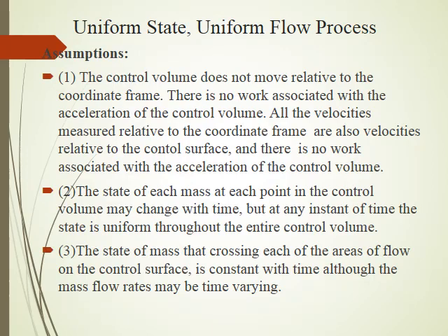See, during steady flow processes, no change occurs within the control volume. It means one does not have to bother about what is going on within the boundaries. Not having to worry about any changes within the control volume with time basically simplifies the analysis. Many processes of interest, however, involve changes within the control volume with time, and such processes are called unsteady flow or transient flow processes. The relations developed for steady flow processes are not applicable to these processes.